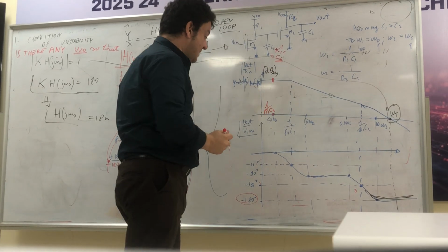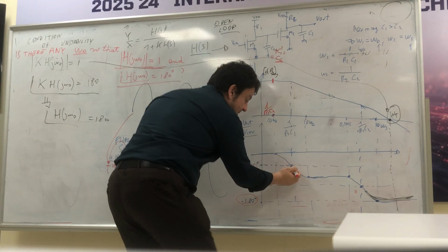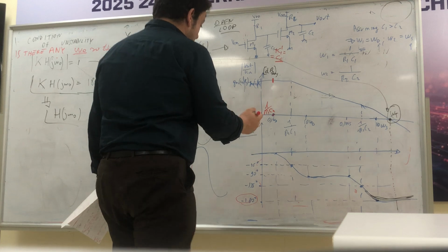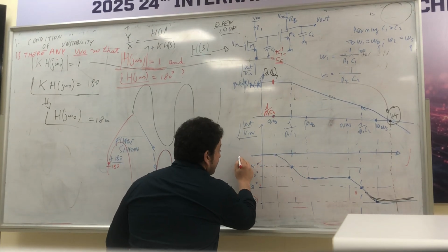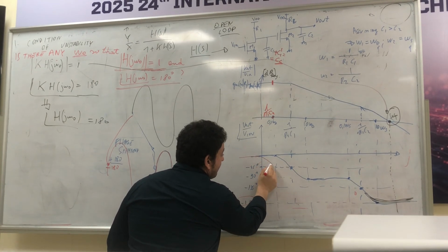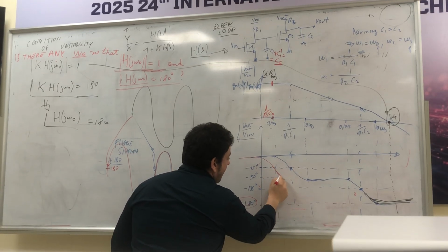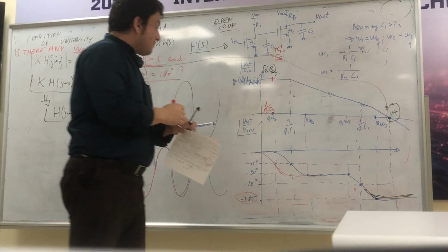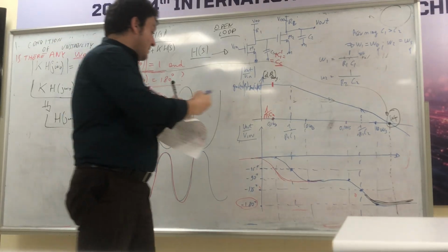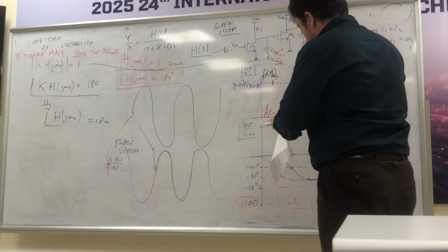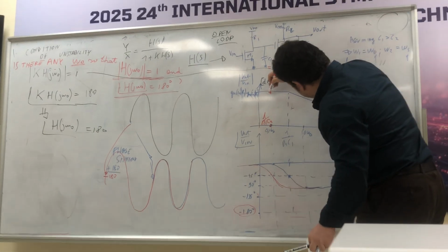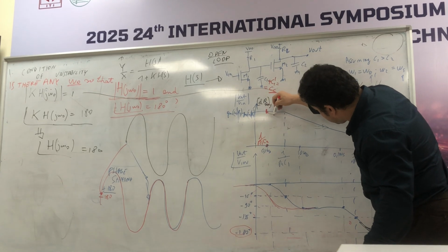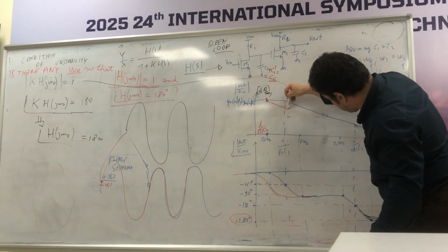Let's consider it here. So what does it mean? It means that this is backshifted, okay? And then continue the same. But what happened to the gain? The gain, because of this higher capacitance, now it's like that. Okay, the pole is here, so actually the inclination now is here.